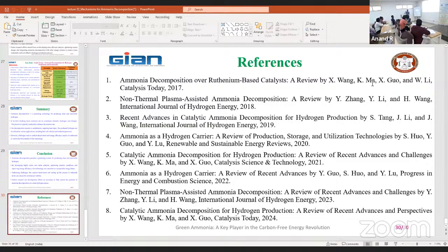Copper is prone to oxidation, and biodiesel contains oxygen. Here, I don't think there is a problem of oxidation, particularly because ammonia contains only nitrogen and hydrogen, but it is corrosive in nature. The property itself is corrosive. So we need to ensure that from the point of storing the fuel in the tank, through the fuel tank to the pump, and then from the pump to the engine components, all the components are exposed to the corrosive environment.